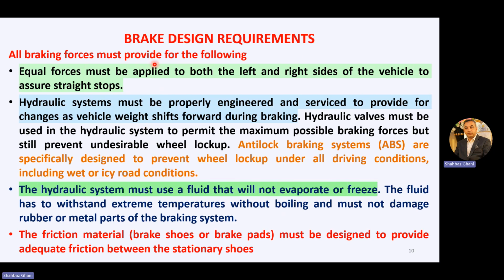Now, brake design requirements. If you are a mechanical engineer or automotive engineer and you have to design a brake, what are the brake design requirements? All braking force must provide for the following. Equal force must be applied to both the left and right side of the vehicle to assure a straight stop.